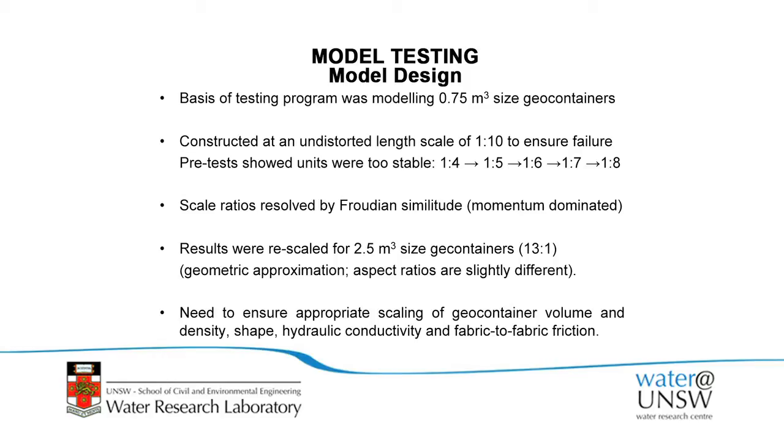Some of the things that we scaled, it's not as simple as just putting a length scale. We seriously considered all the dimensions of the containers, plus the volume, the density, the shape of the containers relative to real world ones, the hydraulic conductivity of the fabric itself, and then the sand we use to fill it in the model. We have to try and scale that. And also the fabric to fabric friction to try and make the friction between the units in the model match or scale up to be equivalent to the friction between the units in the real world.